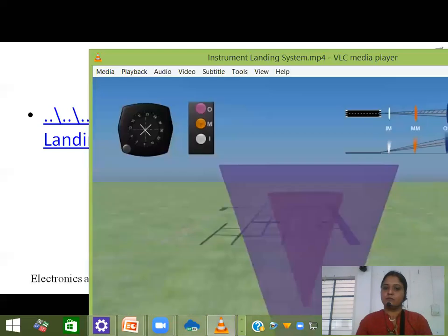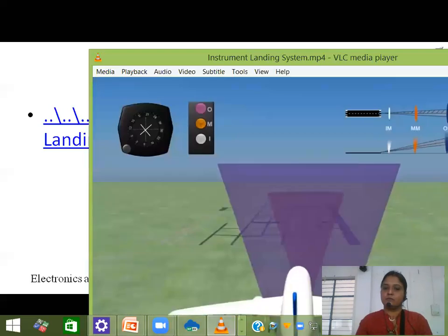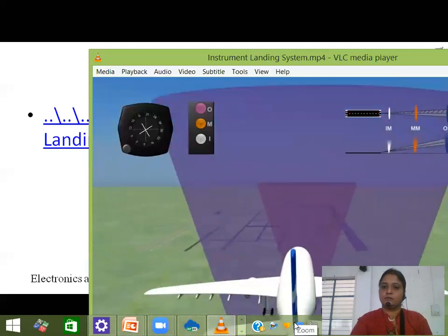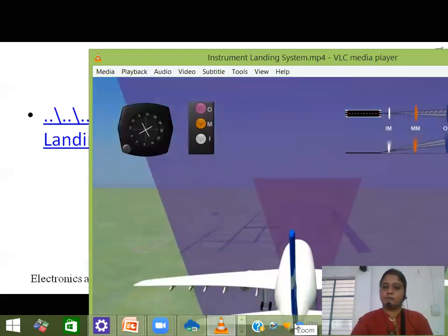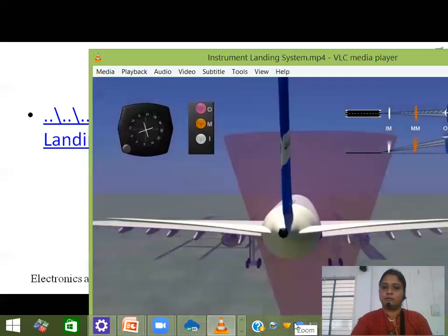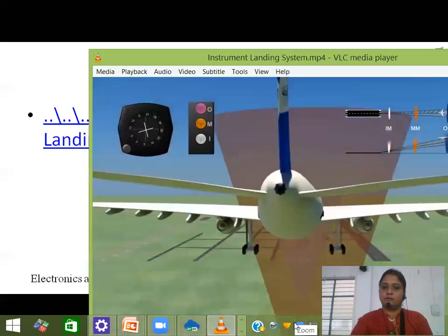When the aircraft passes over the outer beacon, a vertically emitted radio signal activates a rapidly flashing blue light on the aircraft's marker beacon receiver. It also produces an audio signal, which is 2 Morse code dashes per second at a low tone.